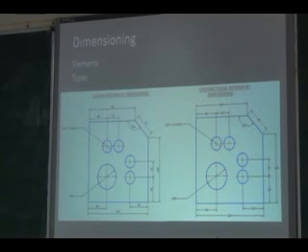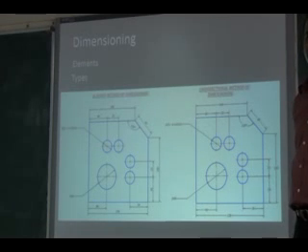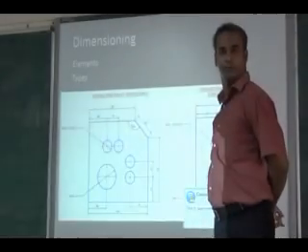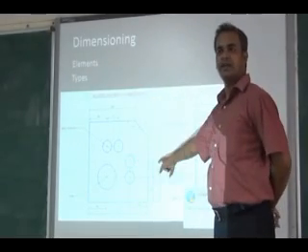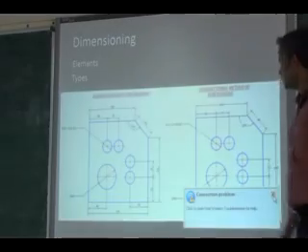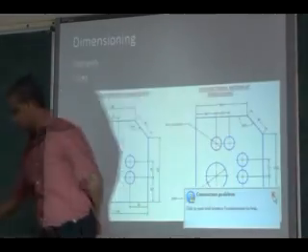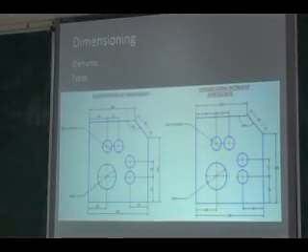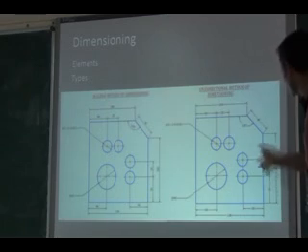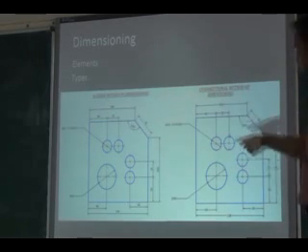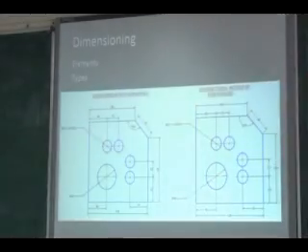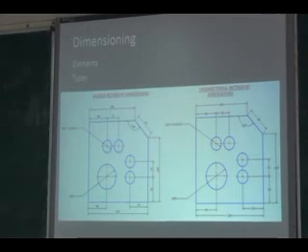Carefully watch the dimension values. In the aligned system, the dimension value is parallel to the dimension line, aligned over the dimension line. In unidirectional, the dimension values will always be horizontal to your drawing. You see here, the dimension value is aligned, it is not horizontal. In unidirectional, whatever value you are writing, the dimension value should be horizontal.